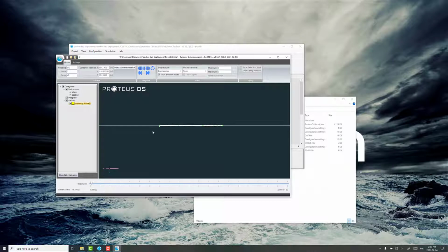And as you can see, this takes a little while. So what I'm going to do is pause, because it's a 6 kilometer long mooring, so it takes a while to follow through the water column. You can click and drag on the slider and get an idea for how the mooring is transitioning through the water column. So you can see the anchor end leading and pulling the mooring down, and it's just touched down at the end there. So the buoy's following along the surface, and it's reached, you know, kind of a profile after having been pulled through the water column.